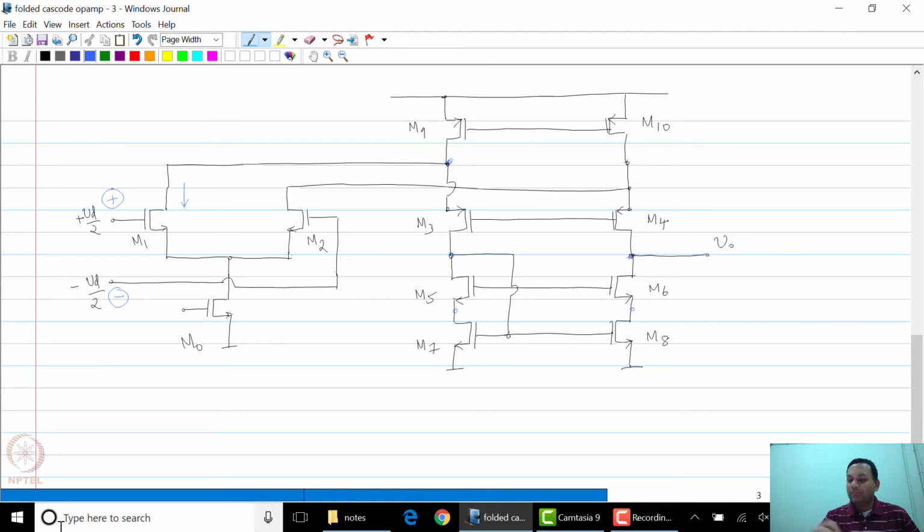So clearly, you expect I1 to pass through these 5 nodes, and of course the output node. So you expect 6 poles in the expression for Vout over I1. And if you look at I2, it of course passes through this node and the output node. And as you can see, I2 only has 2 poles. And now these two currents get summed at the output.